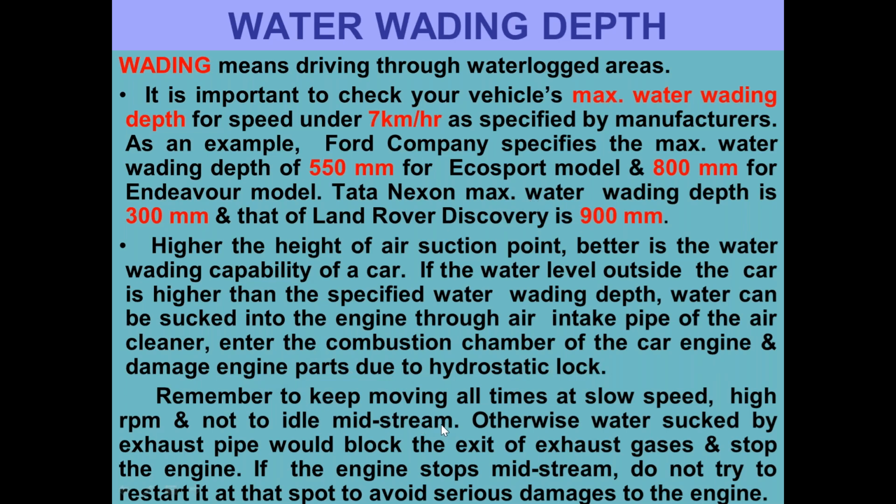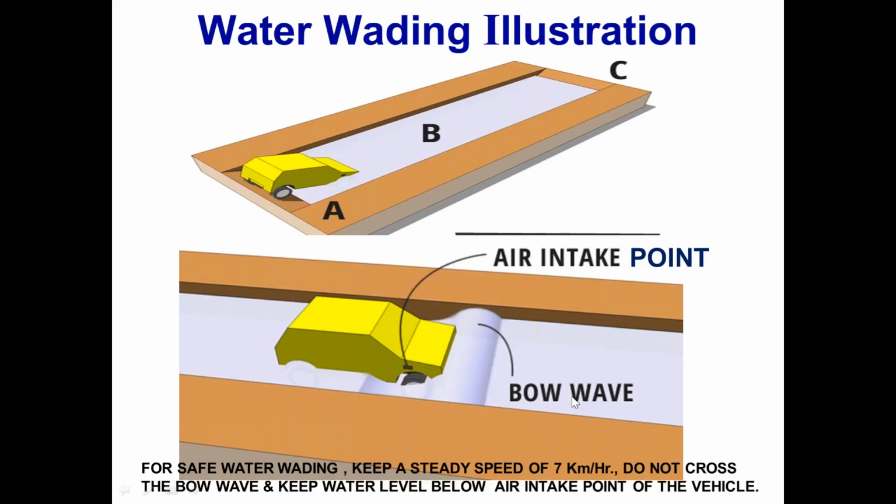Remember to keep moving at all times at low speed, high RPM, and not to idle midstream. Otherwise, water sucked in by the exhaust pipe would block the exit of exhaust gases and stop the engine. If the engine stops midstream, do not try to restart it at that spot, to avoid serious damage to the engine. Here is the illustration of water wading.